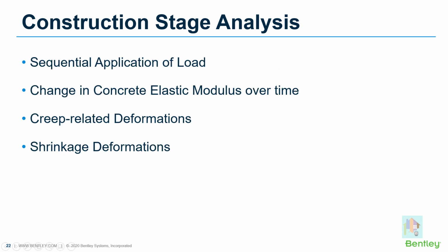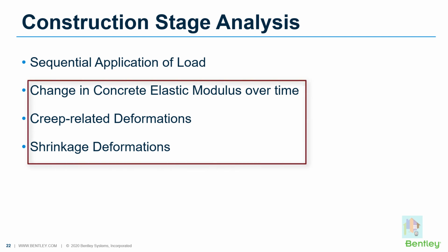Now, the question is why we need to consider this phased analysis. The reason is to consider the effect of sequential load application on the structural behavior and to consider the creep and shrinkage related deformation along with the change of concrete modulus over time. The last part is termed time-dependent effects.